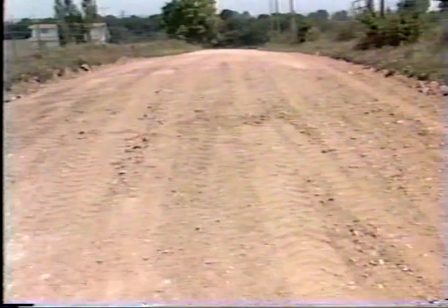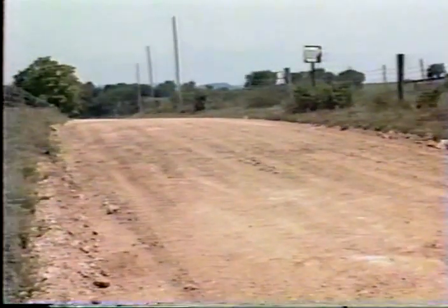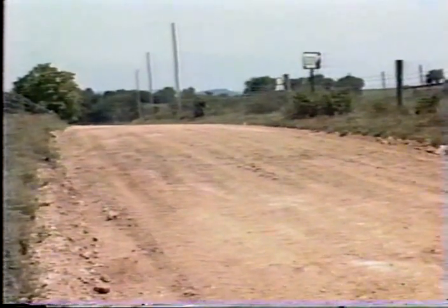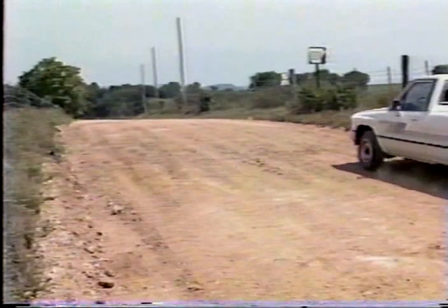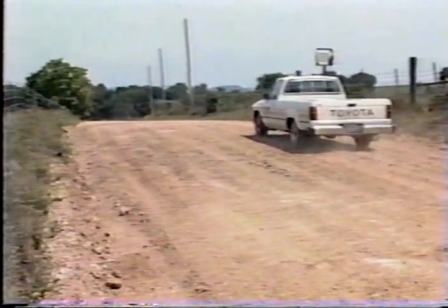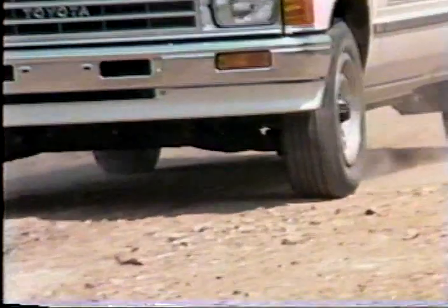Once the roadway has been properly reshaped, the wearing surface must be compacted. The use of a rubber-tired roller, grid roller, or water truck is recommended. Traffic will also compact the roadway, but a rubber-tired roller is considered best. Whatever means of compacting are used, make sure that you do not destroy the crown of the road by making passes down the center line.